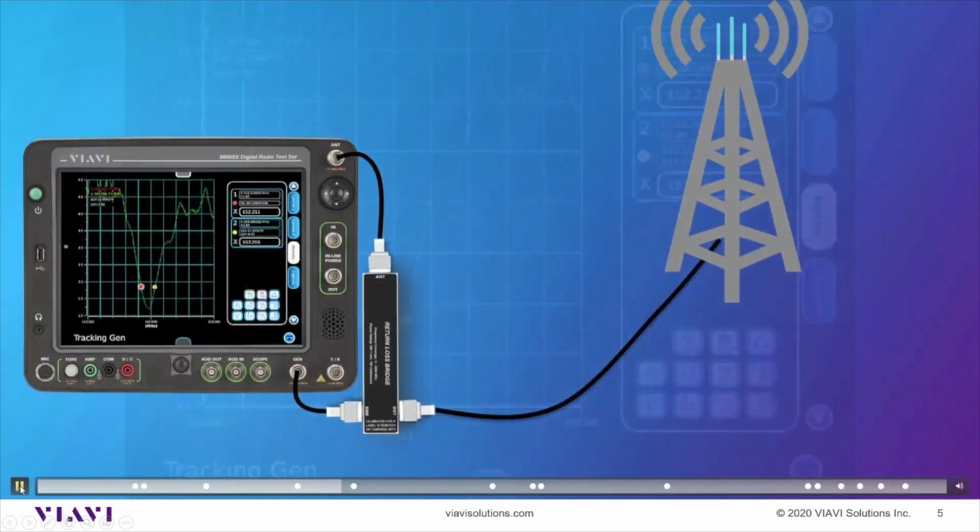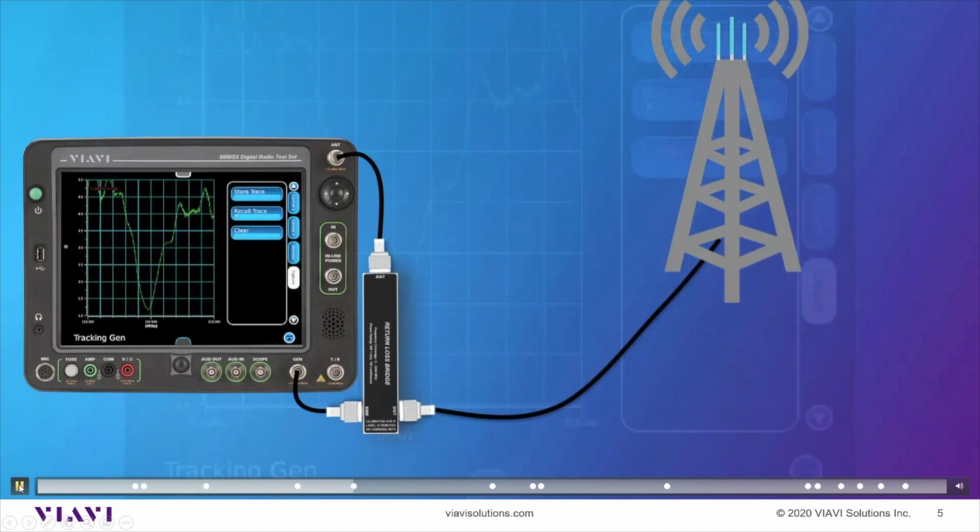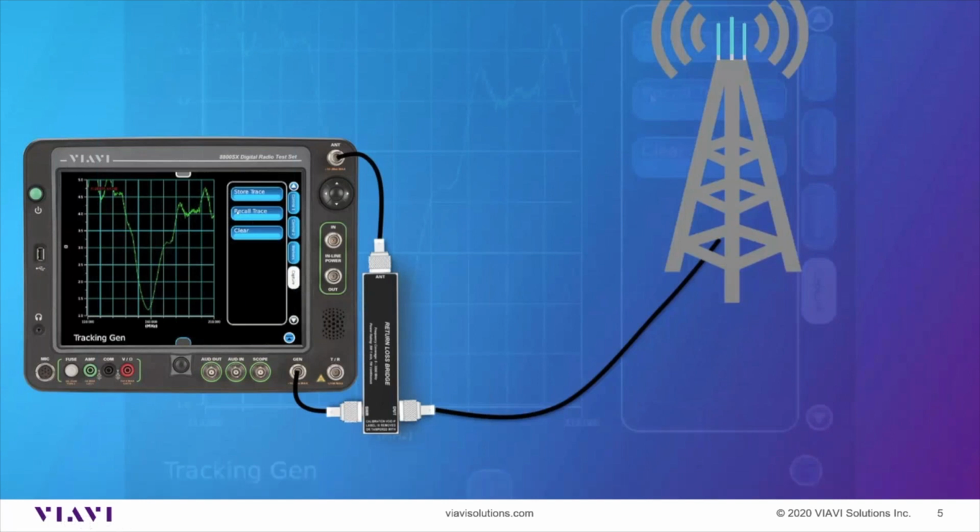Now, one of the other things that we can do, we talked about that compare mode earlier when we were talking about our duplexer and how you can save traces. So we're going to go through the process here. Let's say you are doing your annual PM and you're going through all of your tests and you get to the point where you're sweeping your antenna or even tuning the duplexer.